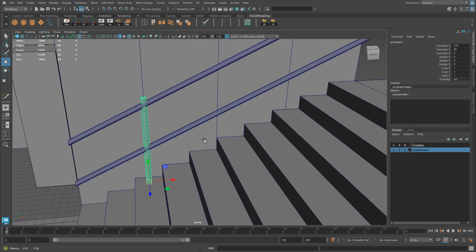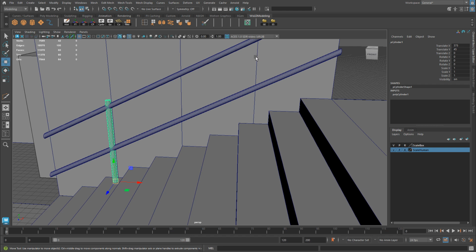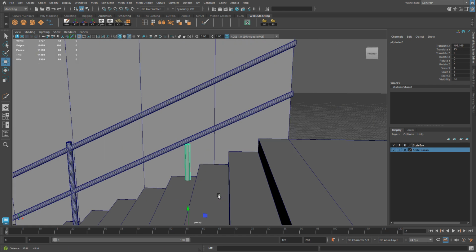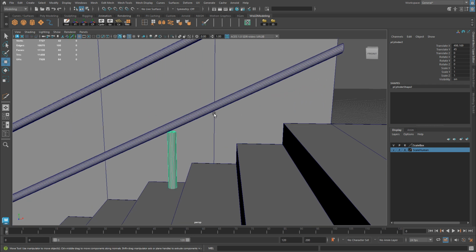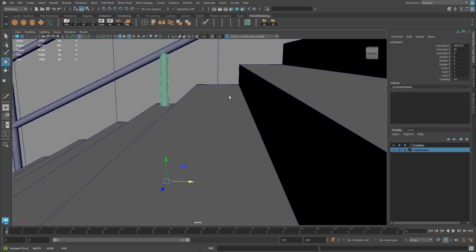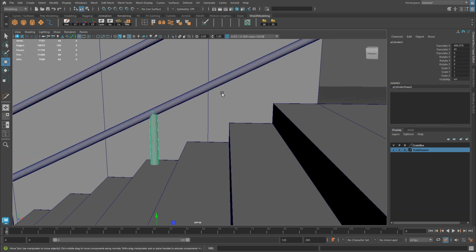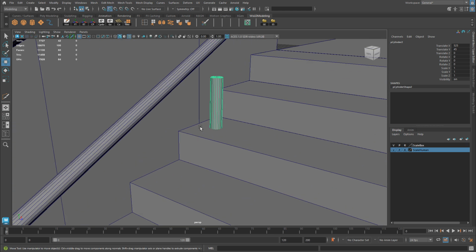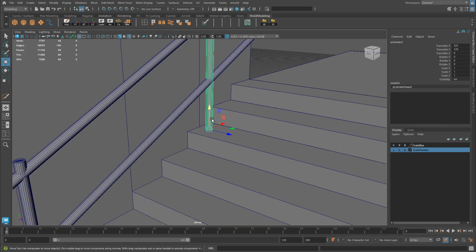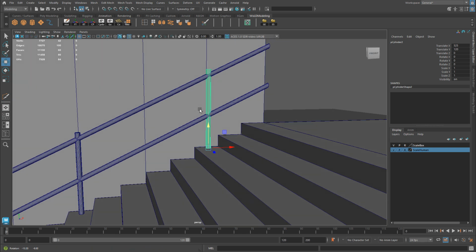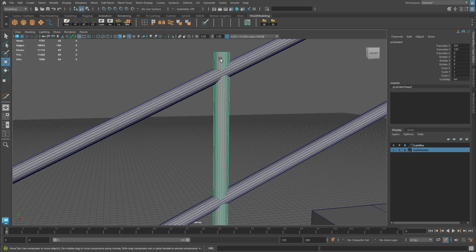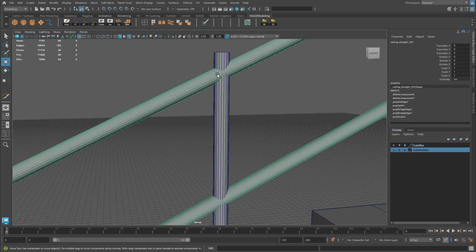And now we just need to adjust the top. I'm going to do this later. Let's go ahead and do the same thing for this edge right here. I'm going to duplicate, Control D, move this railing. Actually, let's go ahead and snap it to this edge. I'm going to activate the x-axis, so it's yellow. C, middle mouse click and drag on this edge, snapped, and now activate the Y. C, middle mouse click and drag on this edge. Now it's snapped on top of the step. I no longer need this wall. Let's go ahead and delete and adjust the tops so they are inside this railing right here.